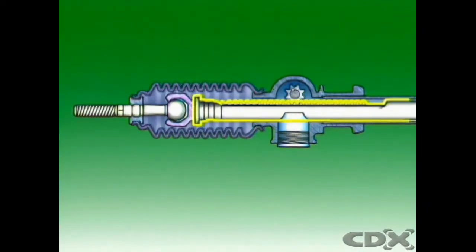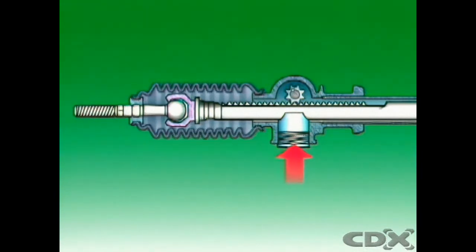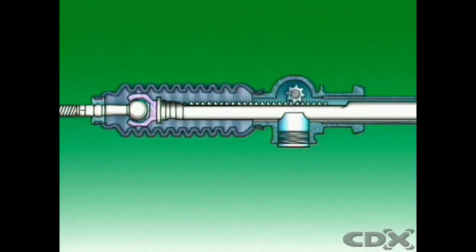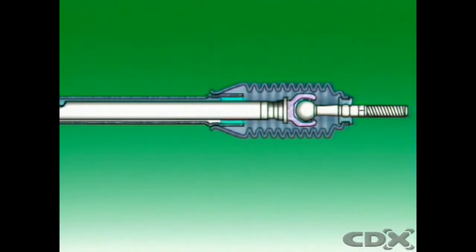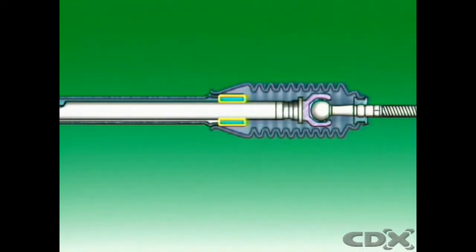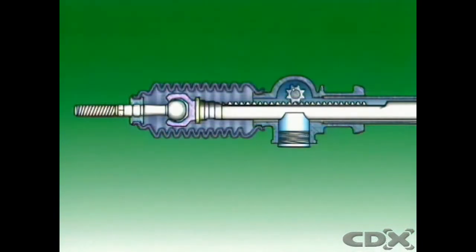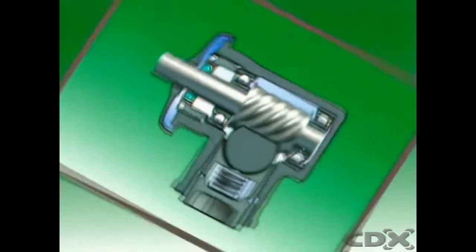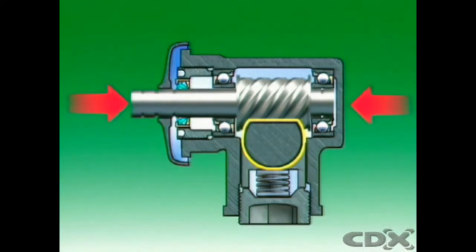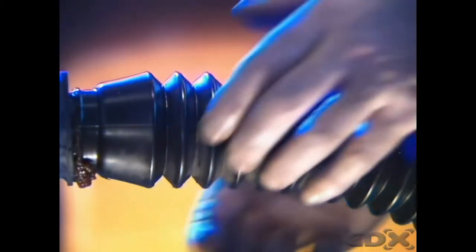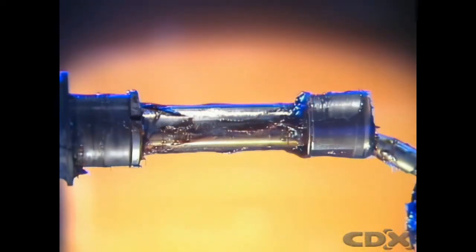The steering rack is supported at the pinion end by being sandwiched between the pinion and a spring-loaded rack guide yoke. This spring-loaded yoke ensures free play is eliminated between the gears, while still allowing for relative movement. The rack is supported at the other end of the rack housing or tube by a bush, normally of nylon. Nylon is used because it has a low coefficient of friction and low wear rate. The pinion is supported by two bearings in the rack housing. These bearings are preloaded to keep the pinion in the correct position, relative to the rack, and to eliminate free play. The rack and pinion steering box is normally lubricated by grease.